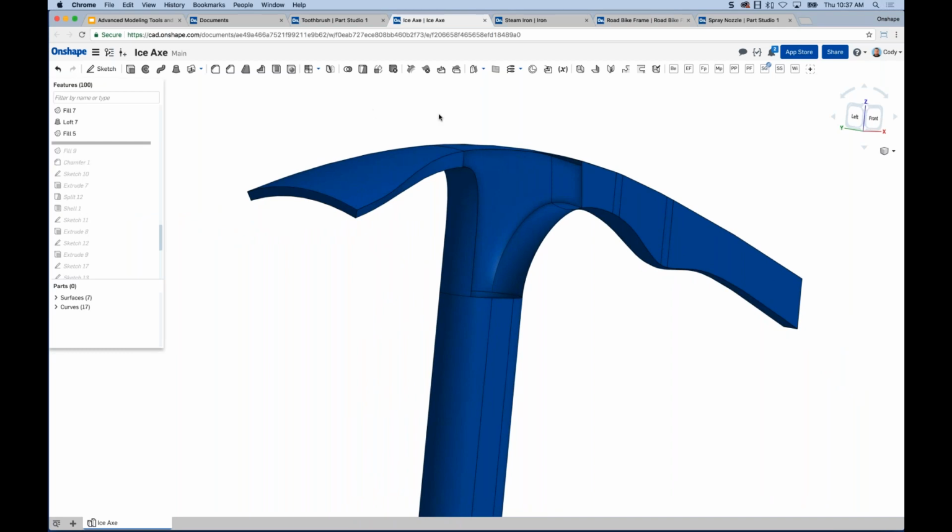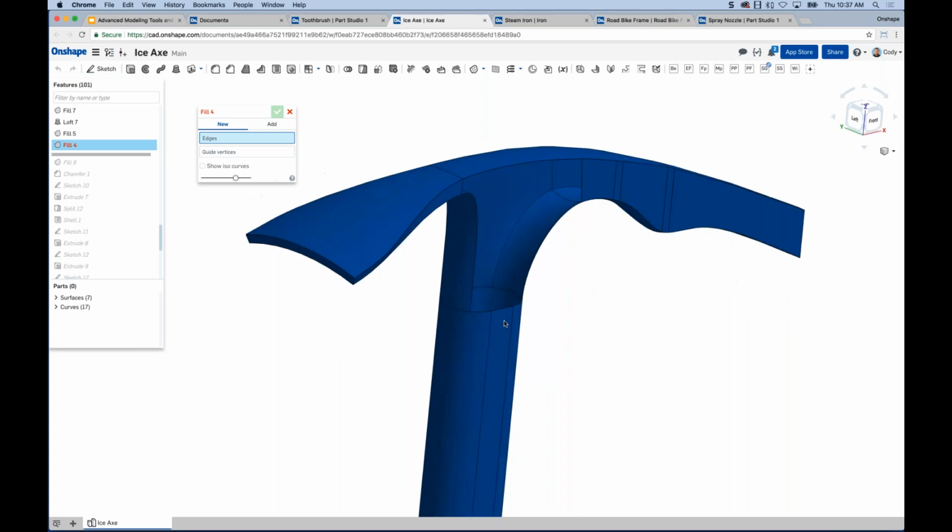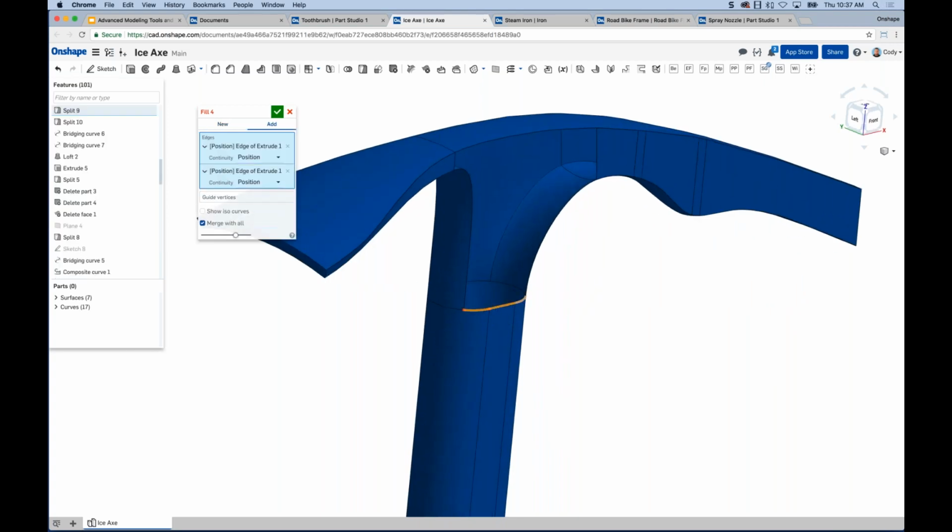The fill command. Now, the key thing with the fill command is you'll find it under offset surface. So in the drop down, you'll see fill, and I just choose the edges that define my boundary. So again, think of this as I'm selecting all these edges. It creates a boundary out of those edges that I click on and then makes a surface out of that boundary, right? So in this example, we'll start at the bottom here and just start selecting these edges.